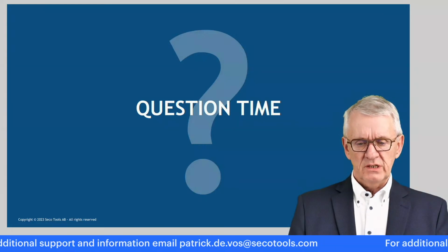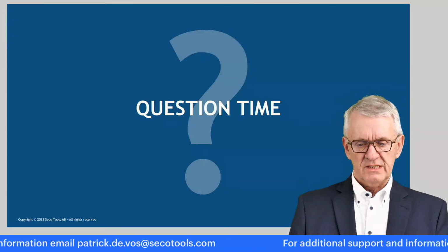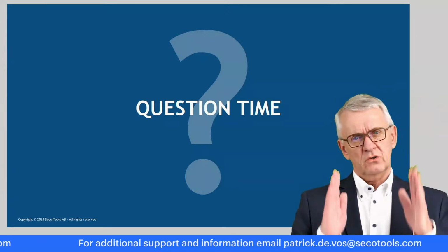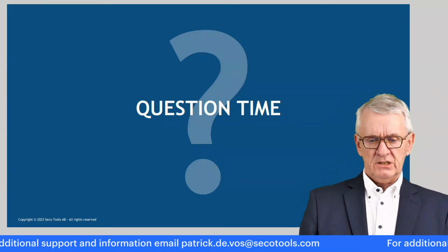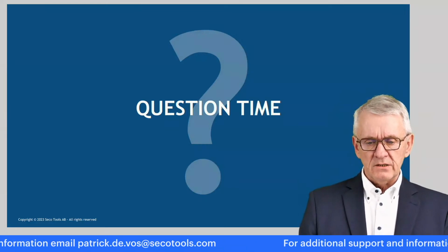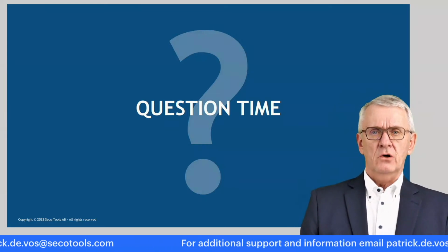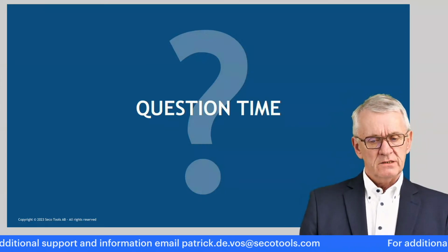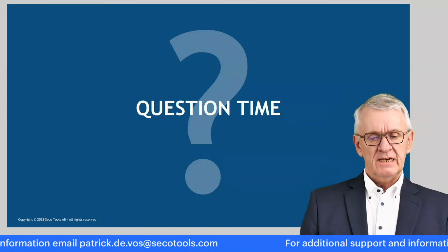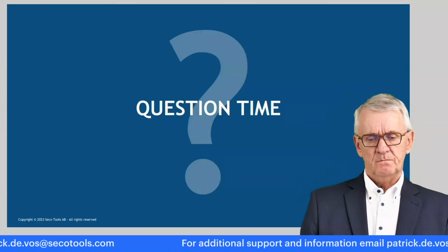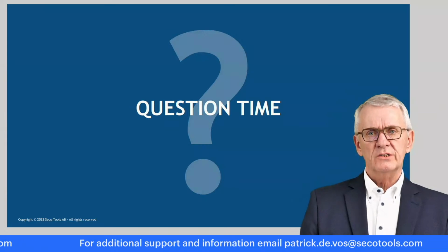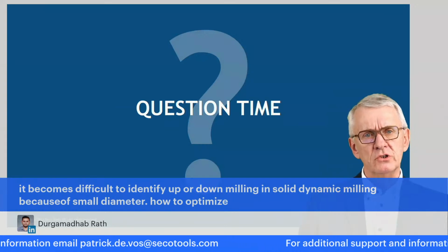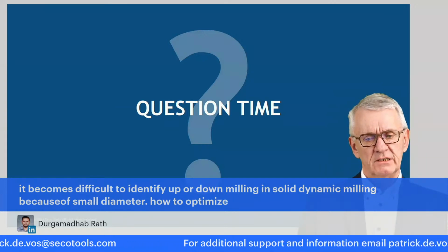Downmilling in conventional machines sometimes becomes a challenge because downmilling draws more power. No. Sorry to be so categoric, but the statement here, no, I do not agree with that. You have impact situations in downmilling, but the power as such is not noticeably affected by that.